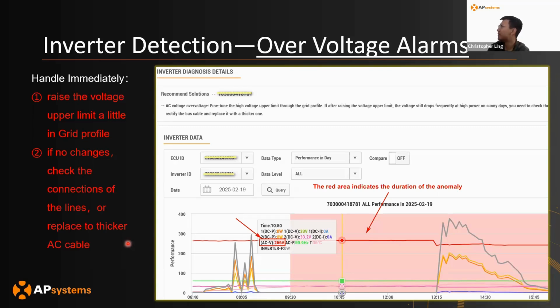I personally don't have many recommendations from a lightning or surge protection perspective. In general, the biggest guidance that we usually give is more from a continuous power rating perspective. From a breaker perspective, it's usually 20 amp or 30 amp breakers that we use. There's usually a maximum number of microinverters that you can put onto a breaker, and those are on the data sheet, but I don't have them off the top of my head. So those are the things that we usually recommend from our side.